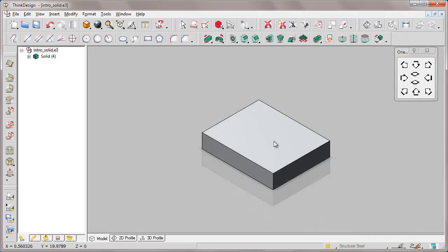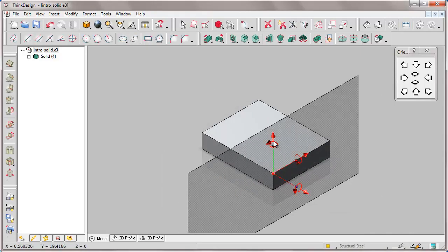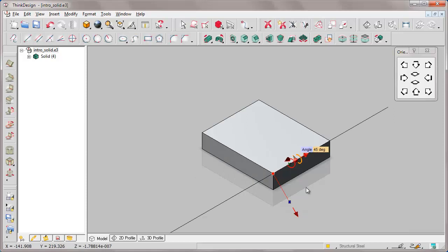Double-click on the round arrows to rotate the work plane by 90 degrees around the axis. Double-click on the arrow of the vector to invert its direction, or by a single click we are allowed to enter the desired value of the angle. All operations useful to position a work plane.